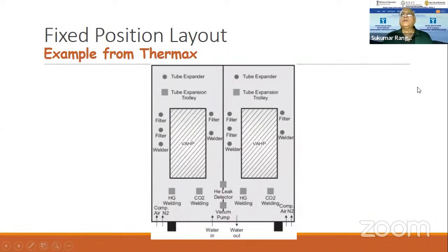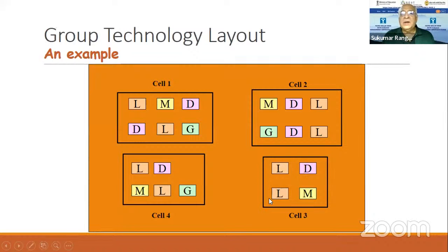Most people use this because, suppose there are 4 products, let us say, in the previous case. The demand for this one has gone down. So they can afford to stop this and move the people to other places, and they don't have to incur running costs on this. Or they can change the number of machines in the cell itself. Suppose the demand for this one doubles. They can close this cell and create one more cell for this. So cellular technology is where there are multiple products, but not too much variety, maybe about 3-4 varieties,